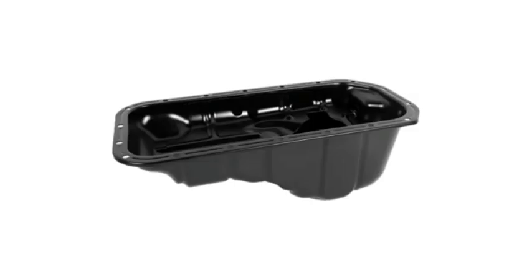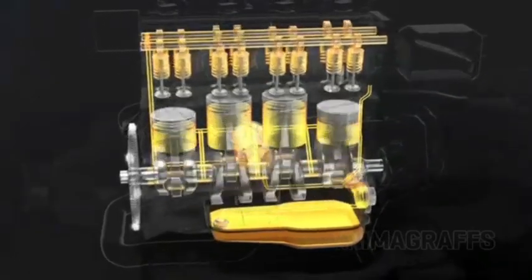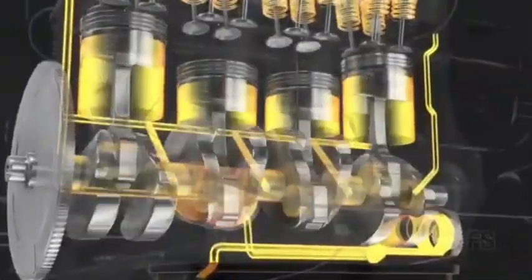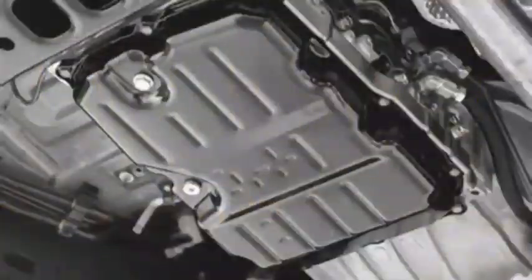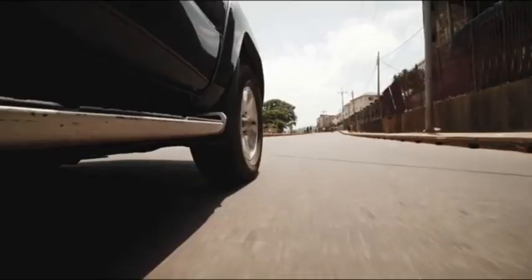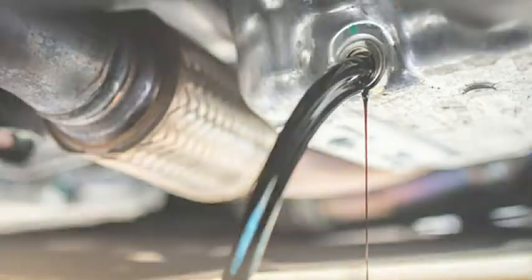The oil pan, also called the sump, is a metal reservoir attached to the bottom of the crankcase. Its primary function is to store engine oil, which is essential for lubricating moving parts inside the engine. As the engine runs, oil is pumped from the oil pan through various oil passages to lubricate the moving components. The oil pan also helps with cooling the oil, as it is exposed to airflow underneath the vehicle while driving. It has a drain plug that allows for easy removal of old oil during oil changes.